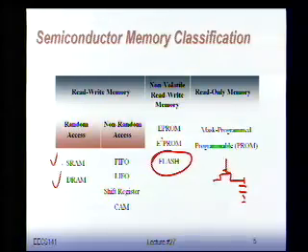Because as you can imagine, programming a threshold or programming a resistor requires some special materials. People use a variety of ferroelectric, piezoelectric, or even dual gate type strategies in flash. It changes the technology, makes it more complex. So actually combining flash memory with processing on the same chip very often is not a good idea, because it makes the cost go up substantially.